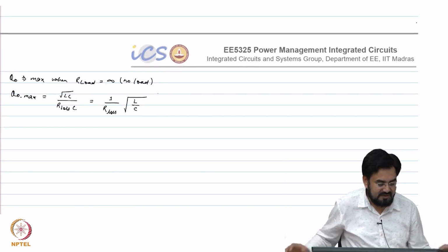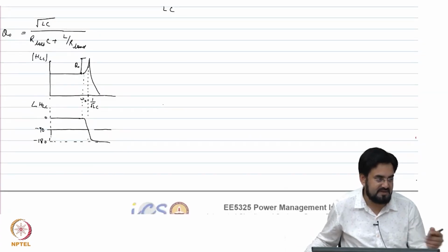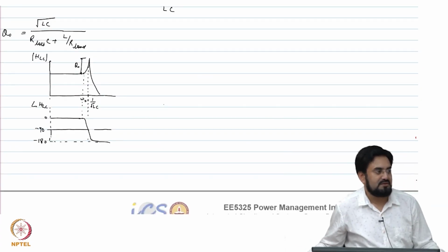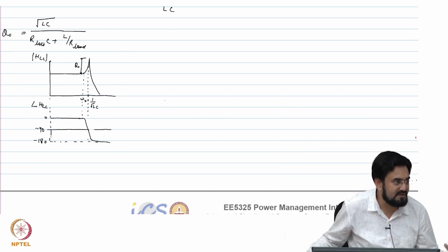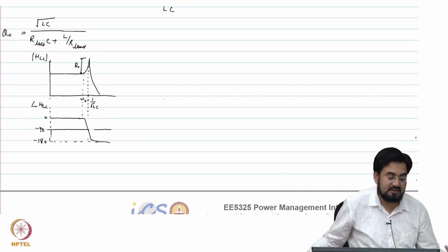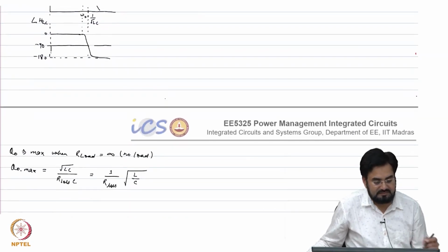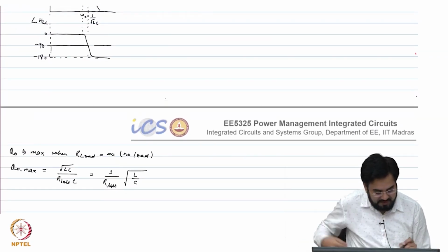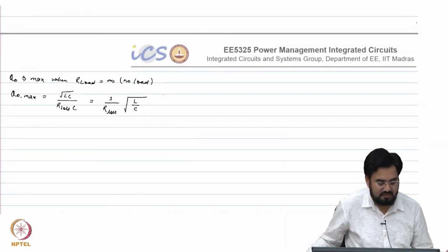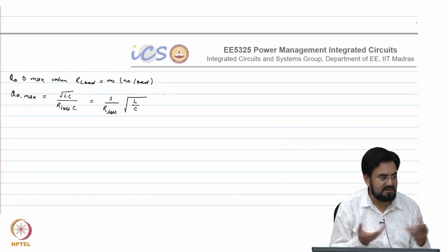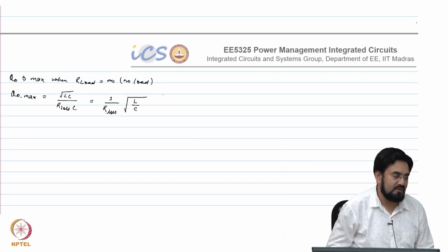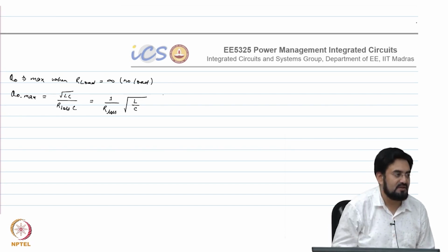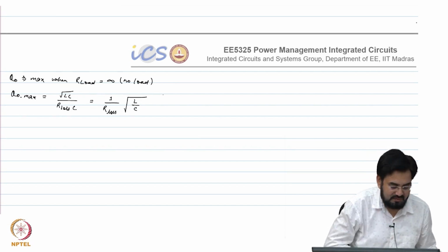So there is a trade off. In terms of the phase shift here, if you are looking at a higher efficiency, you have to reduce the losses, which means you have to choose the inductor with the low ESR, DCR, and MOSFETs with the very low RDS on. So your Q naught will be max under no load condition, and that's where you assume it's a worst case when you analyze the stability, because at omega naught your phase drop will be larger at higher Q naught.